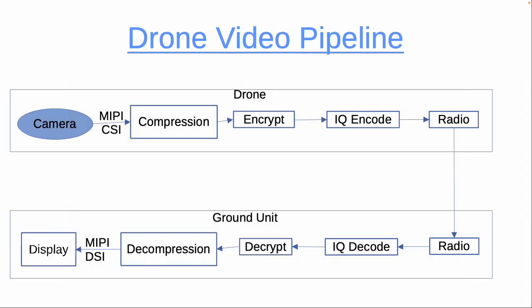Let's talk about another drone application. People want to do drone controllers. It's basically an asymmetric application. You have a very low bandwidth going up to the drone. It's absolutely critical that those commands get through correctly. Much higher bandwidth video comes from the drone back to the ground. It's okay if you lose a few pixels.